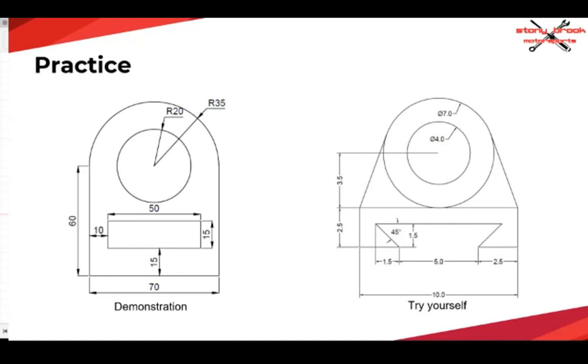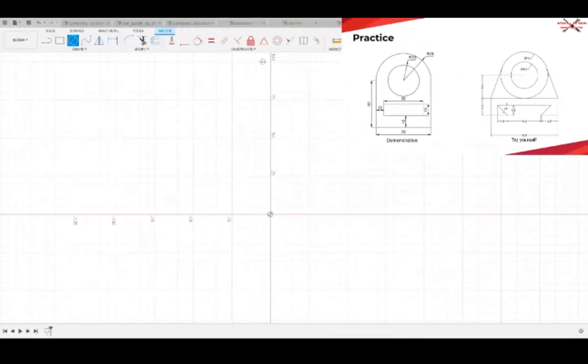That's something you're going to learn in Mech 203 when they go over general dimensioning and tolerancing, or GD&T, which is absolutely crucial to understanding a lot of the intricacies of CAD drawings and why they can seem a little strange at times, because there's a lot of stuff that's often implied but not actually directly stated, such as the implication of a center line here, which implies that the entirety of this part is symmetric about its center line. It's not explicitly stated, but it's implicitly shown via the way the dimensions are set. So, back to the little demonstration.